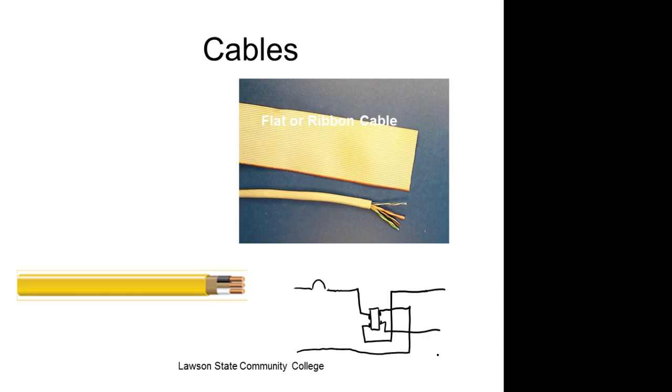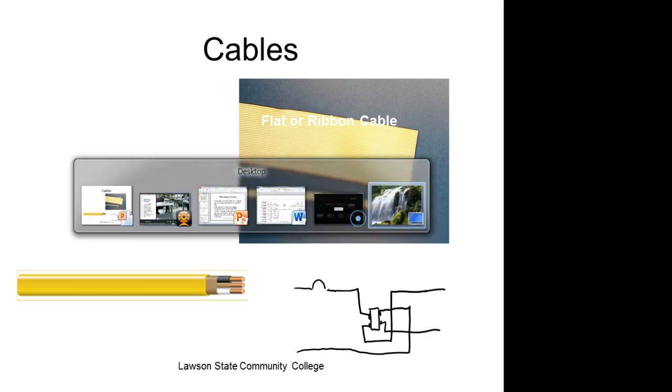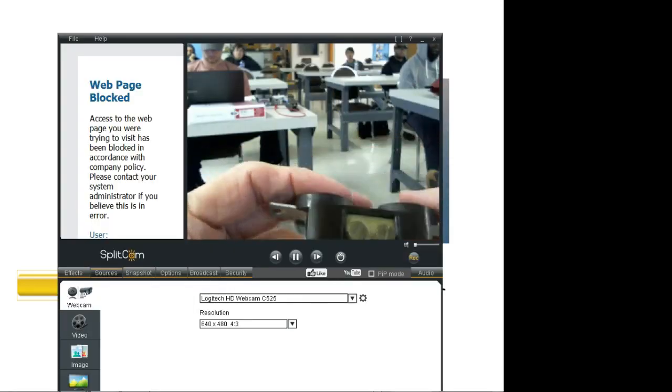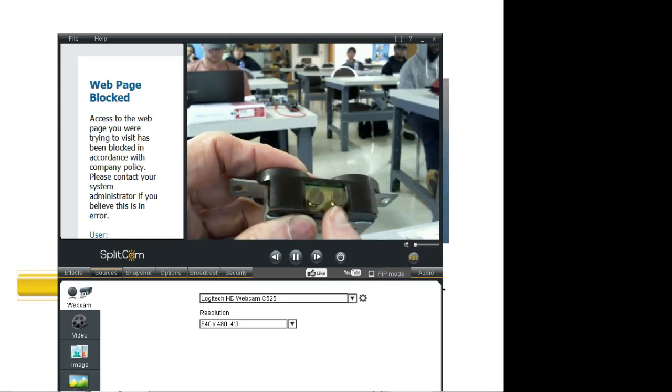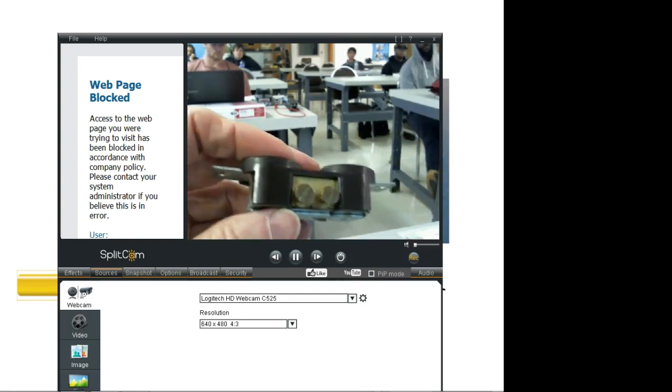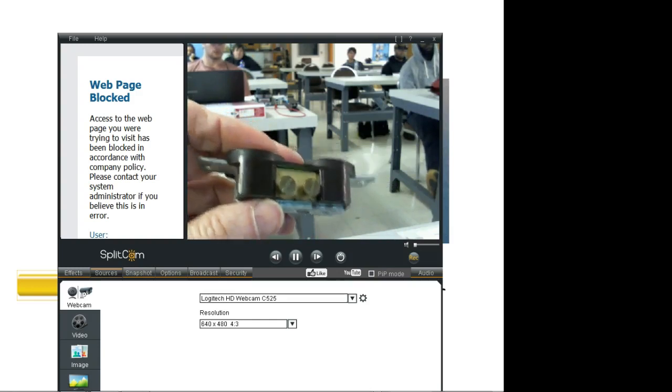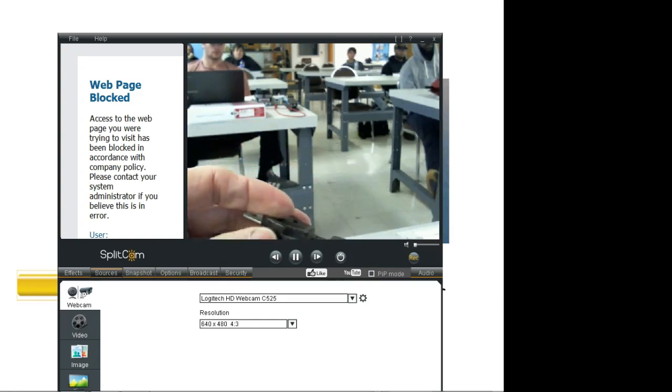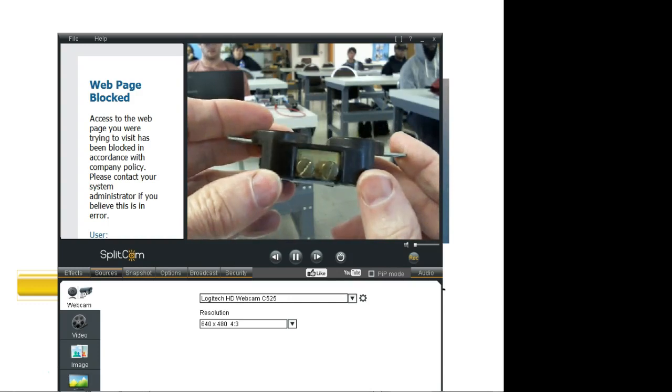This is parallel, guys. But if these screws become loose, you're going to lose whatever plugs are down line, right? You understand what I'm saying? So let's say my wire comes loose out of this one, and this is feeding all the other plugs. Well, what happens, it'll work up to this plug, but none of the plugs down below that will work, right? And that's what happened with my wife's air fryer.